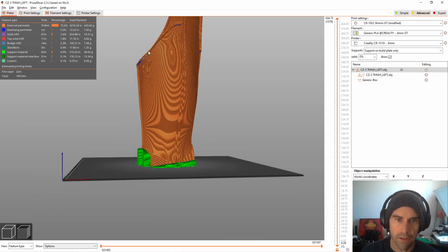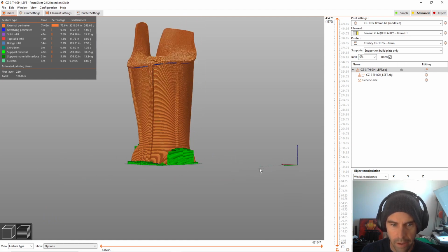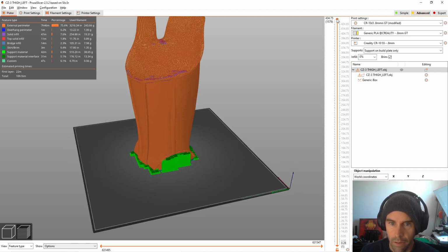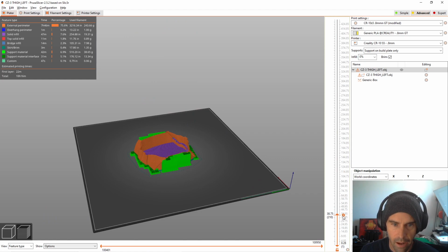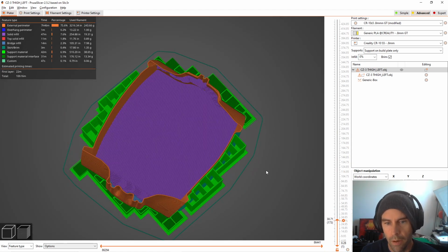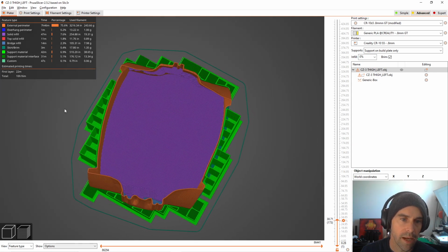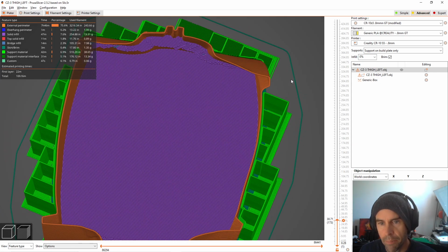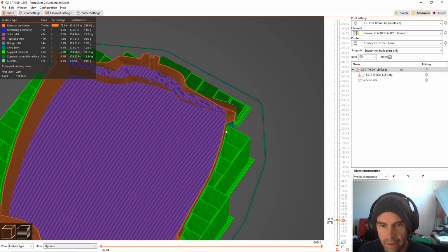And you can see how I blocked all the material. So it supports this little bottom bit here, which if you come down, you can see when I was talking about the 10 millimeter support pattern, see how big these spaces are here? That's a 10 millimeter gap between these little blocks, which is plenty for this. And then the 70% spacing, that is this gap here between the part and the support material.